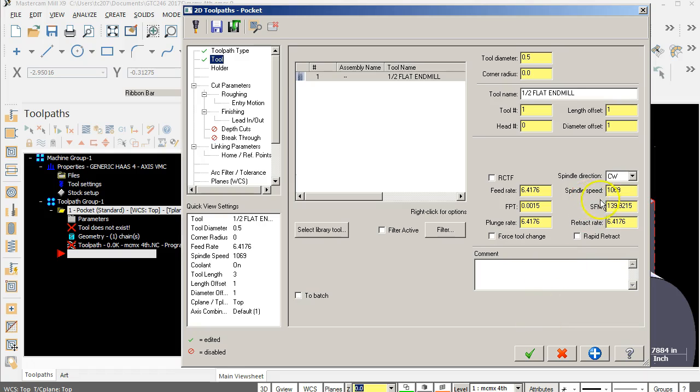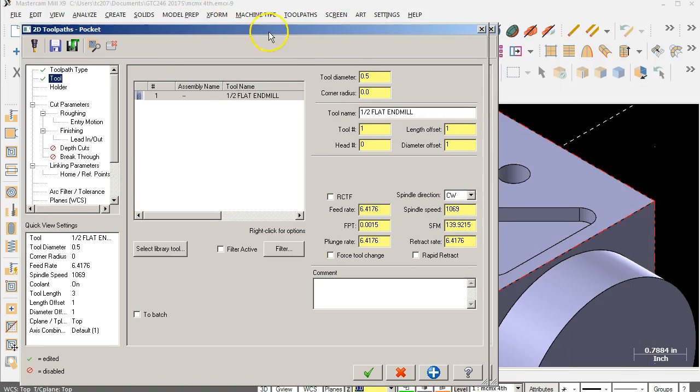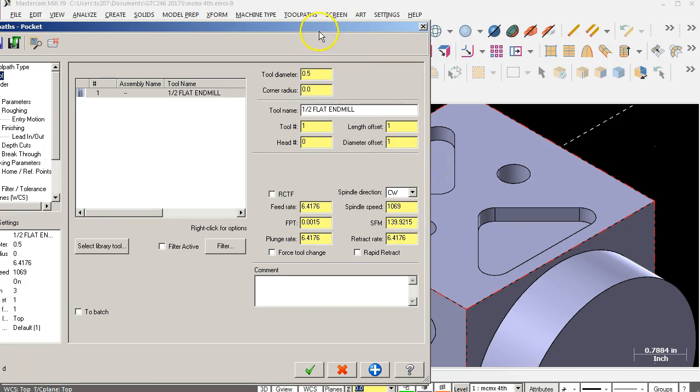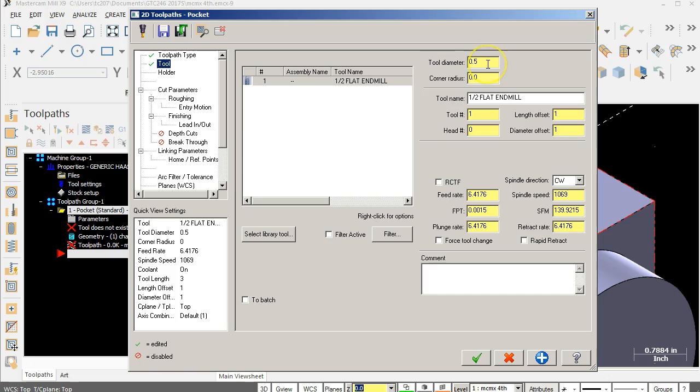Going into aluminum, and we know that this is unsupported. The other question that I didn't address is this probably isn't long enough to put a tailstock on. 4 inches, having that extra support, they're not going to really gain in rigidity, and it's another thing in the setup, and would also need to have the center drilled hole at the center of the part for the center to go in to support.